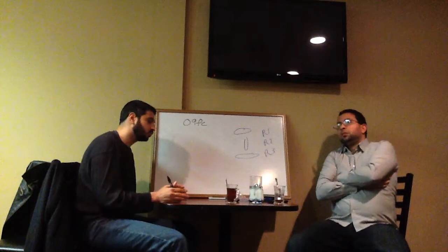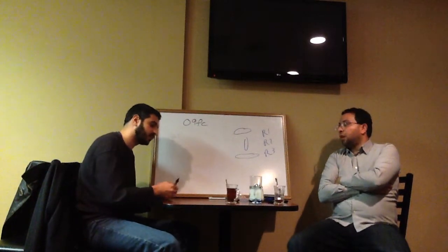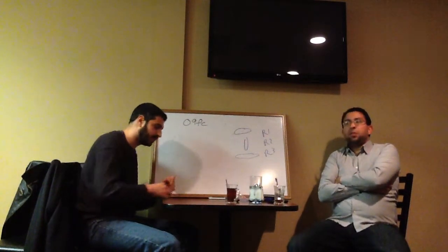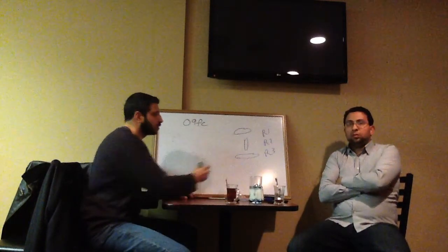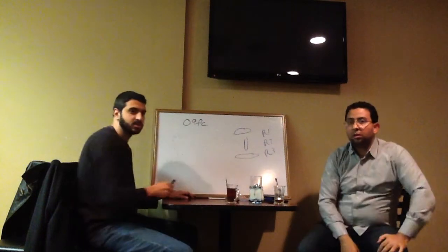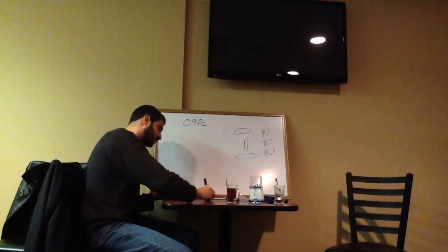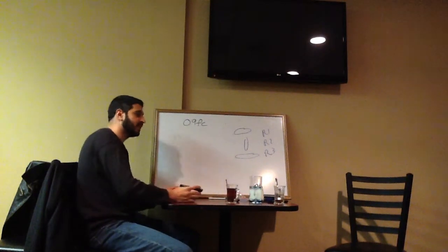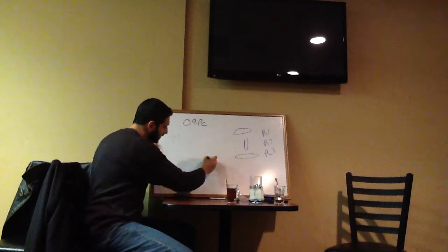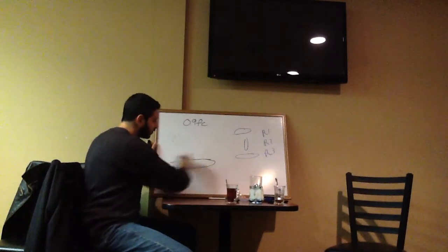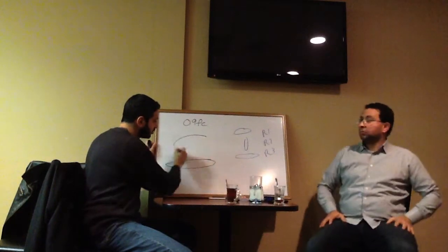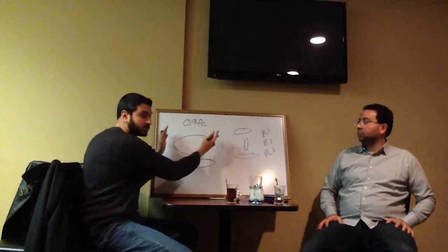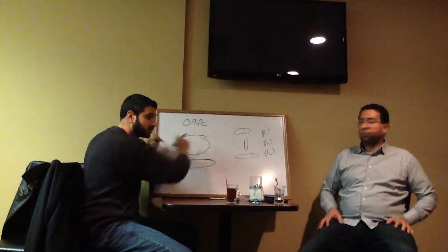When you go to a manufacturer's website, they'll have a cut sheet, a catalog sheet, the specification, and usually they'll have the distribution type on there. So R1, R2, R3 is kind of the general stuff, but they'll have specifically that this light has this pattern. So you can see that this light lights further away and kind of narrow against the roadway. Another light might be like this shape, where it lights further out but less distance across.